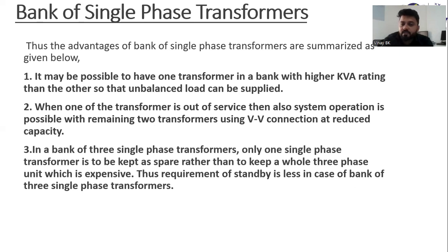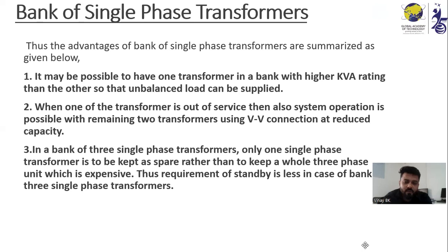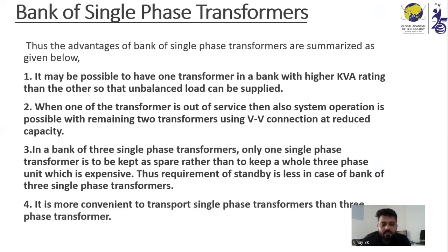In a bank of single-phase transformers, only one single-phase transformer needs to be kept as a spare, rather than keeping a whole three-phase unit, which is expensive. Thus, the requirement of standby is less in the case of a bank of single-phase transformers. And the last is that it is more convenient to transport single-phase transformers than three-phase transformers. So these are the advantages of a bank of single-phase transformers.